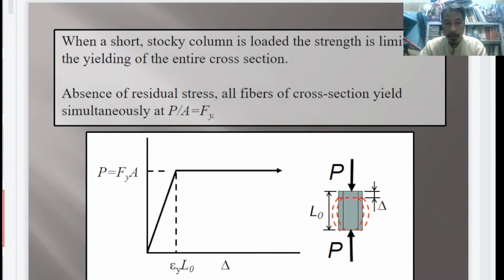the stress. Okay. So very basic theory, compressive in its manner, as you can see on the diagram. All fibers of the cross section yield simultaneously at that. So that is our theory. Uniformly, simultaneously, the cross section. So in your figure, you are actually seeing the member that is a W shape, W beam or W shape section. Okay.